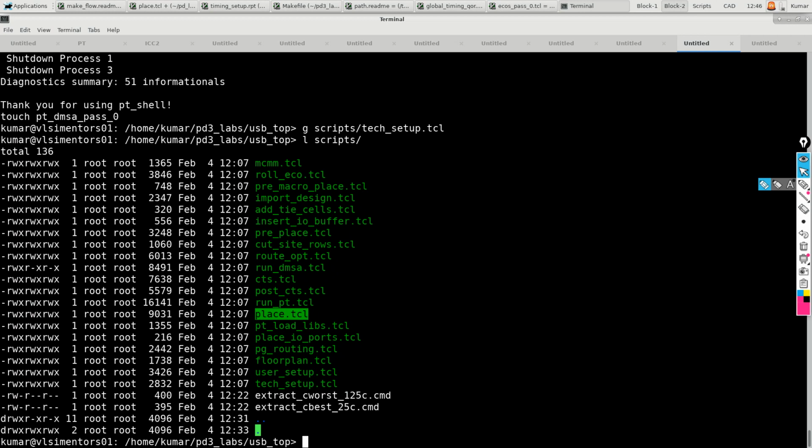No. So maybe there is a clarity missing actually, but congestion purely depends on your design and the types of cells that you use, whether it's a 6 track, 7.5 track, 8 track, 10 track, and what is the area that is occupied by PG routing. So there are many things that you need to look at. I'm still sticking to the same answer. It's kind of 0.5 before CTS, and 1 before routing. Okay, yeah, sure. Thank you.